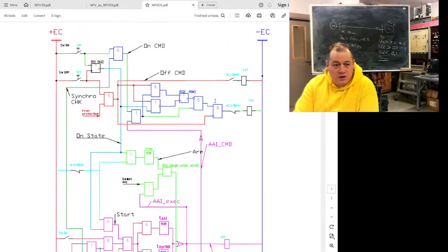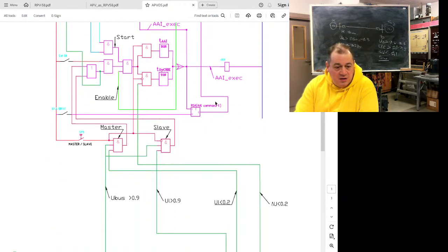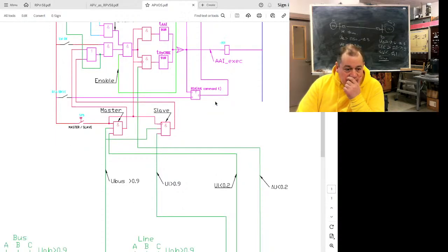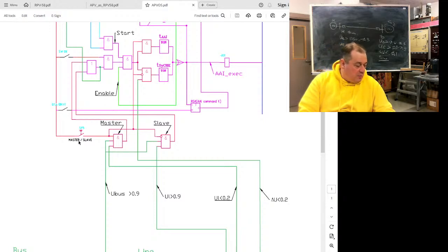What happens in slave mode? Slave mode is more complex, in case the switch is in the slave position. It's good practice to periodically switch roles, because the master switch is loaded much more aggressively. On a persistent fault, the master switch will disconnect the full short circuit current. The slave works in milder conditions, so it's good practice to periodically switch roles.